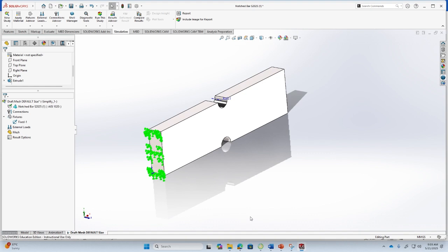So essentially this is then solved in matrix form, where this will be the material stiffness as well as the geometric stiffness included in the K, and then it will solve that system of equations. So here on these boundaries the U value will be prescribed. Now the next step is to apply the load.